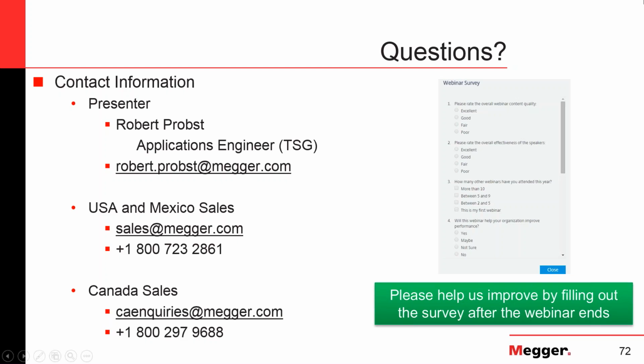Only to add to that, in differential protection schemes, as an example, transformer differential protection schemes, you're looking for faults inside the zone of protection. This can be handled by either increasing the amount of current in the primary and decreasing the secondary, but those are run with slope tests. To do that is either single phase or polyphase. That means you need multiple boxes to do this. In addition, specifically for transformer protection, there's a common test called the harmonic restraint test, which validates that the protection scheme will not trip on transformer energization.